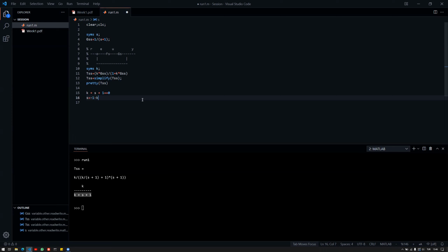The other thing would be then also to place the poles with a strategy that serves a certain purpose. Now, if I choose a pole distribution that has a certain settling time or overshoot properties, that would also be nice. So that would be the second step. For today, and for the sake of introduction and simplicity, we will stick to the stability part, but that's not all of it. So now I can see that there might be problems with stability if I have a certain controller and a closed loop system.